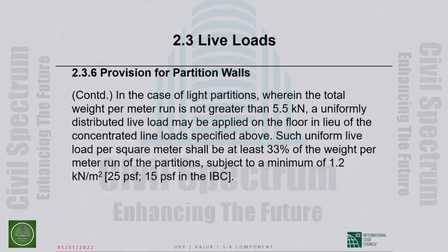Such uniform live load per square meter shall be at least 33% of the weight per meter run of partitions, subject to a minimum.